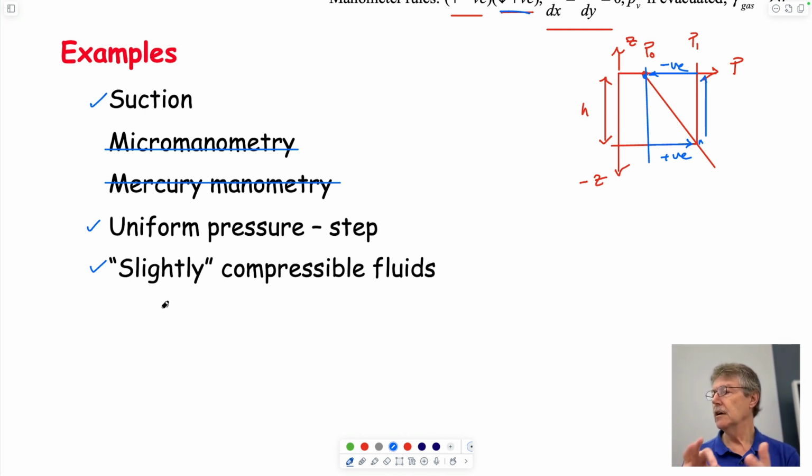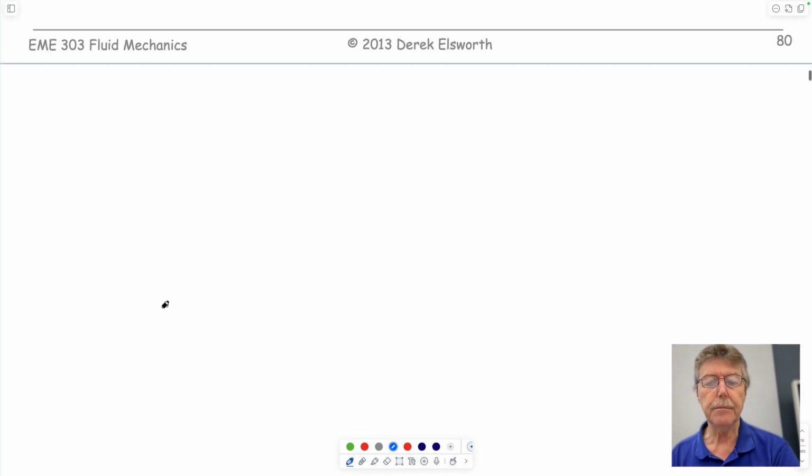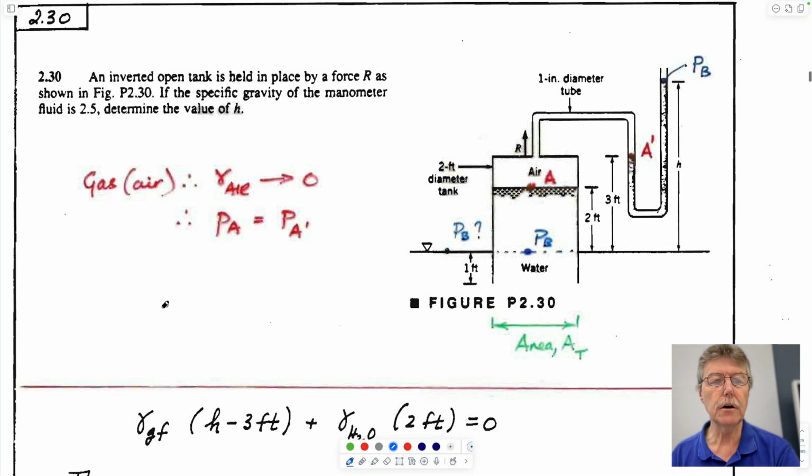It essentially is. If you have brake fluid in a piston, when you pump on the brakes, you feel a resistance. That's because that fluid, brake fluid rather than water, doesn't compress. If the brake cylinder was filled with air or any gas, it would have a long travel before it exerted any force through the lines that grab the calipers. So let's go through some examples.